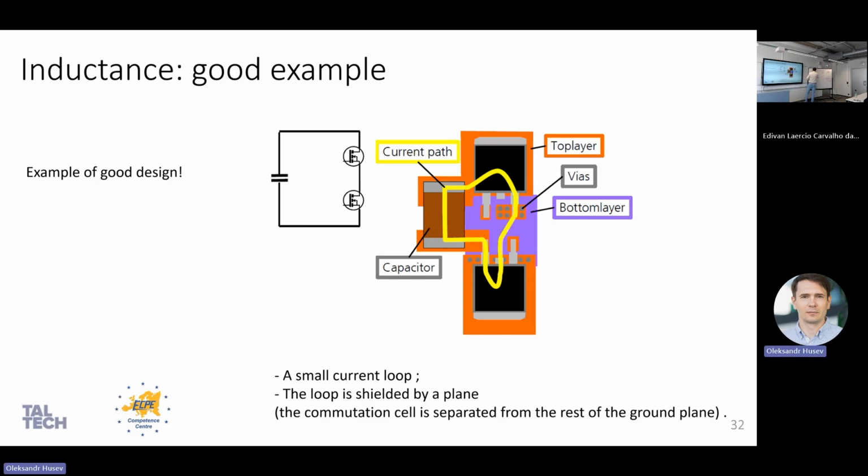Always understand that this is also a basic example, but quite useful, I think. Just imagine that, due to some limitations, sometimes people ask, you have electrolytic capacitors placed something like this. And you have your half-bridge transistor somewhere here. And definitely you have plus and minus, so you need to connect something like this, right? But how can you minimize your switching cell if you don't have the option to move this?